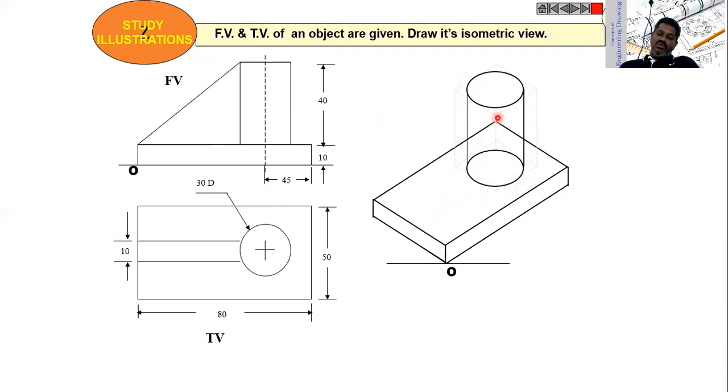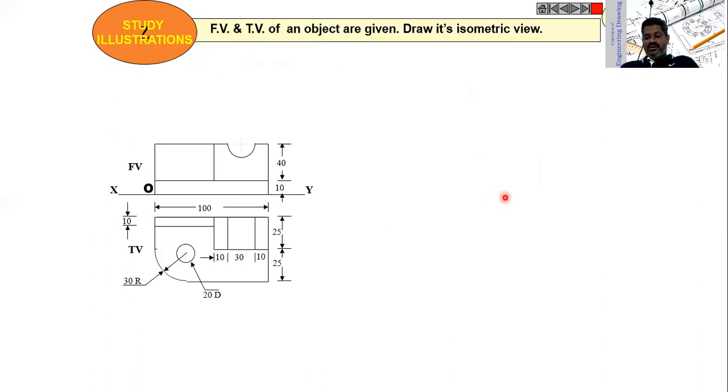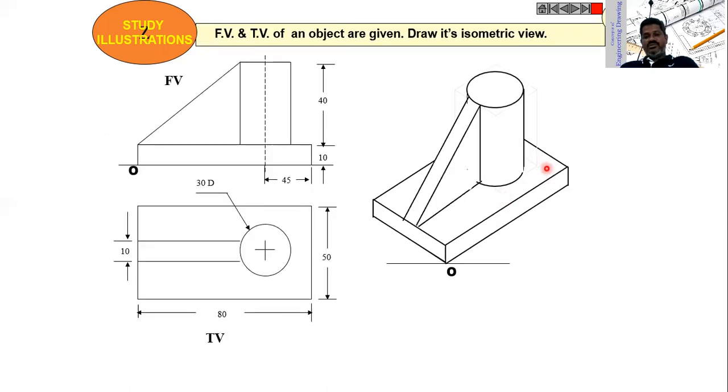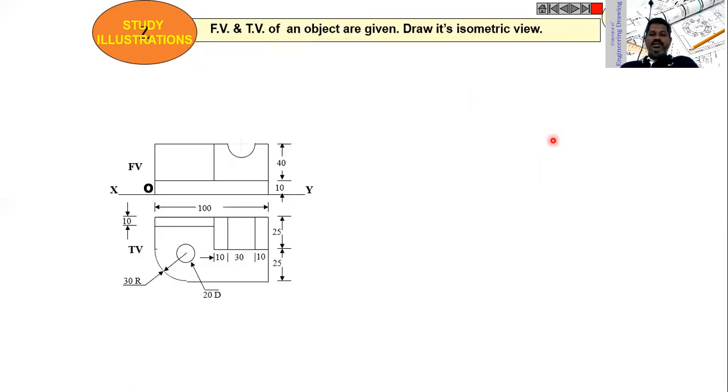Now there is one more web here, exactly at the mid, and you locate midpoint here and locate midpoint here, construct the web, and you also indicate the edge here and also indicate edge here like this. So now erase whatever the lines which are not visible in the three-dimensional view. It looks like this. Now let me move further.